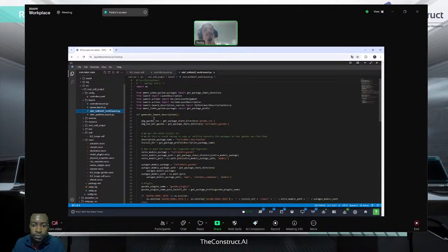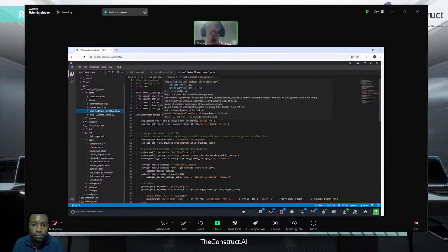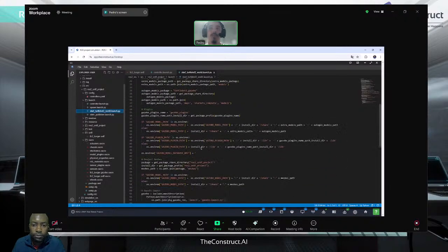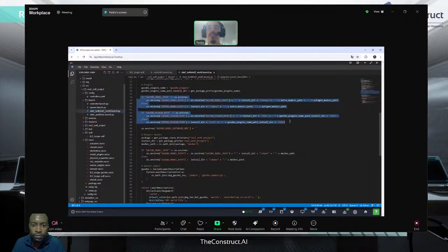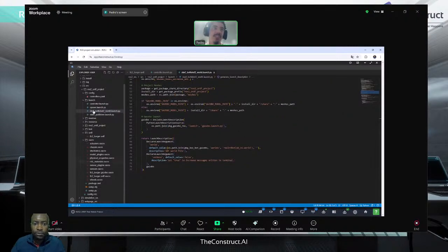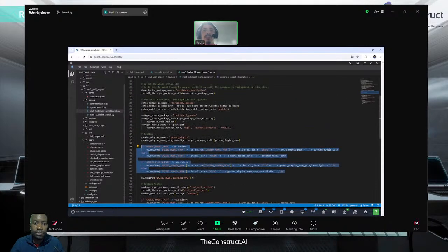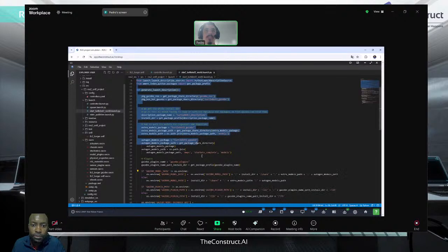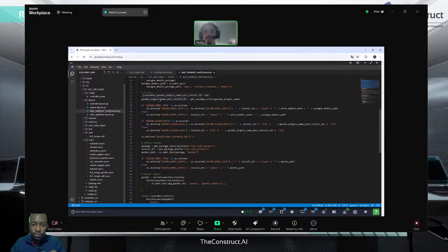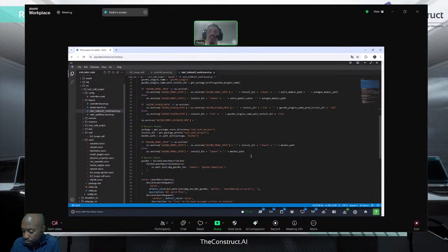And I need to remake the start launch file to start Gazebo because I need to include the STL files. So I searched in these files that the project gave me. I found the start script and I changed some things. So here I have all the code that already exists and some things like the path for the STL files for the LiDAR and the LiDAR support.